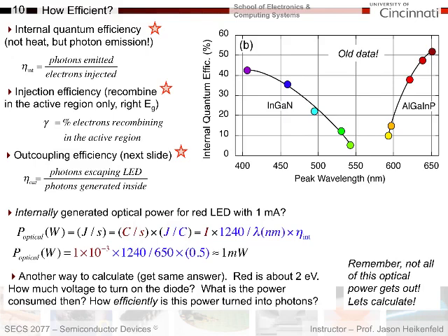Well, this helps me because if I drive this with 1 milliamp, that's my coulombs per second. So I'll put 1 milliamp in there. How do I get joules per coulomb? Well, for red light, I know that my energy is 1240 over lambda, right? So I can put that in here for my joules. And if I need my coulomb, I can get my internal quantum efficiency, which has units of coulombs in the denominator here, which is exactly what I want to get per coulomb.